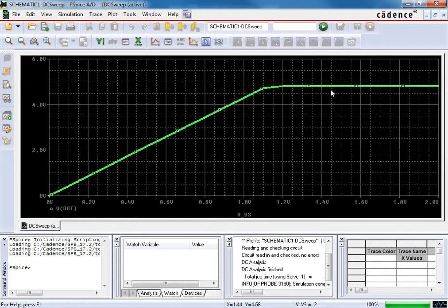And so in circuits 1, we of course said it would saturate to 5 volts, but now we're actually dealing with real devices as opposed to ideal op amps, and so it's not going to go all the way up to 5 volts. It's going to go to something less than 5 volts because the op amp actually needs voltage as well in order to operate properly. There's transistors and other things in there that you have to bias with voltages. Alright, so that being said, we get an expected result here. We have a nice straight line. If you computed the slope of this line, which maybe we'll do in a second, the slope should be what your gain is.